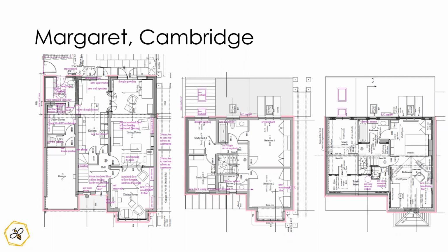Part of the underfloor has got ceramic tiles. I'm not so worried about that, but we do have some engineered oak, and I don't really want that to be affected by that. Keep it below 40. Have that on the circuit from the heat pump, which won't go above. And how do we get enough hot water? I'm not sure. Oh no, the hot water's on a separate circuit.